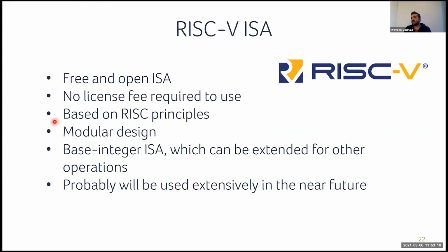It's based on reduced instruction set computer principles, just like ARM or MIPS. And it has a modular design: there is a base integer ISA that is there for all implementations, but then it can be easily extended.